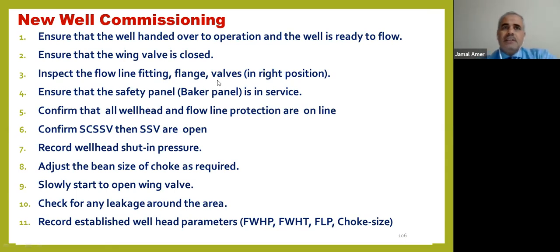One example from my experience. One time I was visiting a Christmas tree to take readings, in a program to visit every 2 days or so. I saw that the Christmas tree had slipped down by 2 or 4 centimeters. So it's very important also to notice this point. If the Christmas tree height changed, also if we have vibrations on the Christmas tree, vibration due to production, of course.